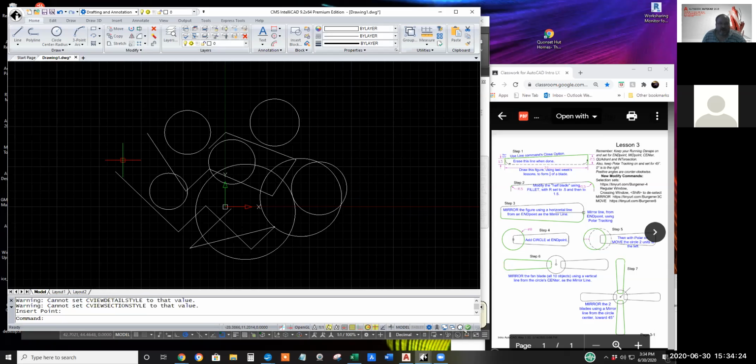And we want entity snap, same as AutoCAD's object snaps, set to the 5 favorites that I have here checked. They're in a different matrix than AutoCAD, but the same names: endpoint, center, intersection, midpoint, and quadrant. Have those checked and running all the time.